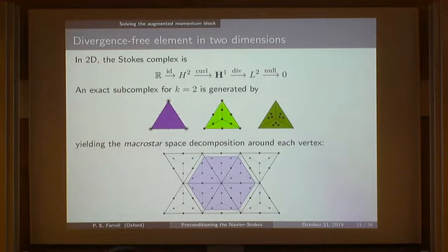So what goes wrong? Experimentally, what goes wrong is that you see oscillations, grid scale oscillations in your velocity. Well, if you don't stabilize, you only stabilize along the normal direction. Well, that's not the streamline direction. Yes, that's right. Usually you stabilize purely in the streamline direction, but you don't. Is there any explanation for this? So it's not changing the discretization to be a Petrov-Galerkin scheme. It's just experimentally fixing or computationally fixing what goes wrong with Galerkin schemes.